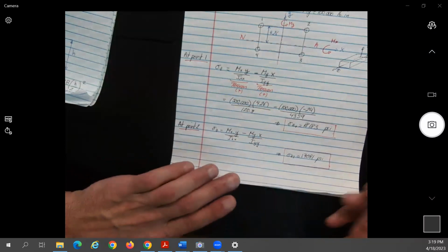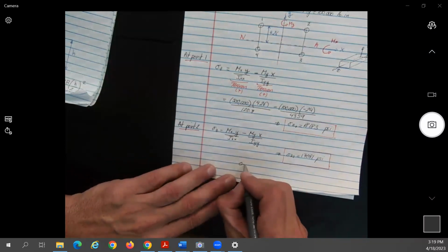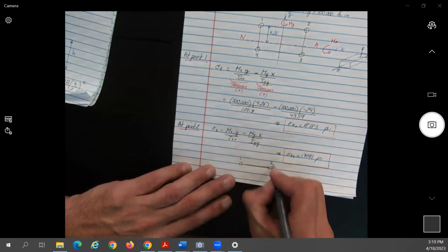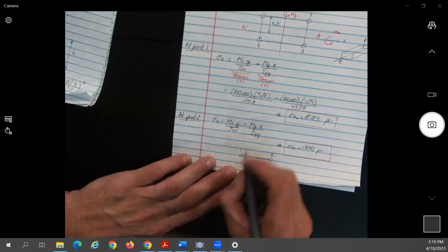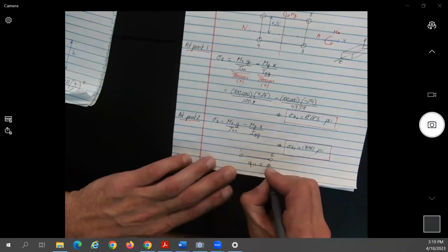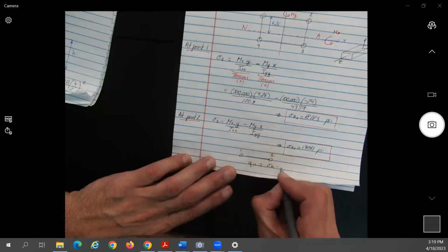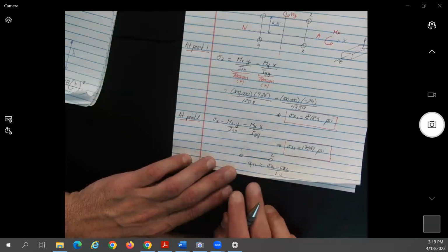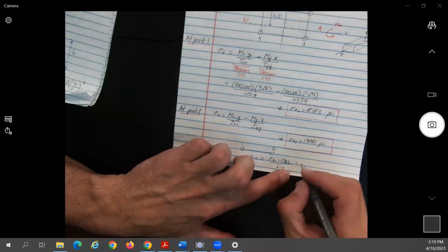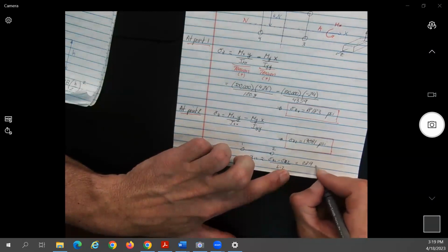Okay, so if you want an approximation of Q12, I'll do a problem in detail because this is the way it's really done in real life, to tell the truth, without using the complete equation. You can say that Q12 is approximately equal to sigma Z1 minus sigma Z2 divided by the length between those two, no? Okay, and what do you get? You said 22 point something? 22.9.